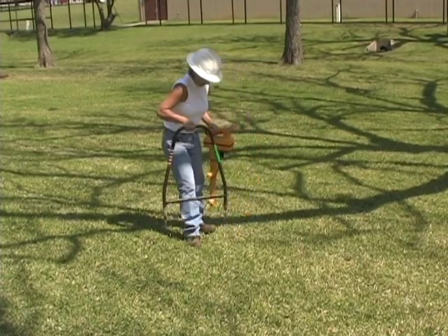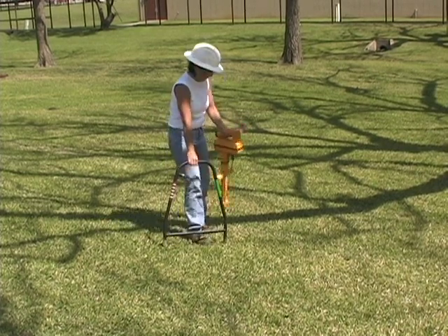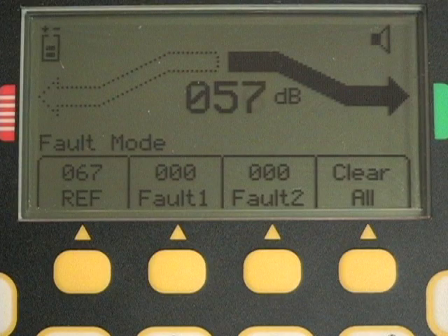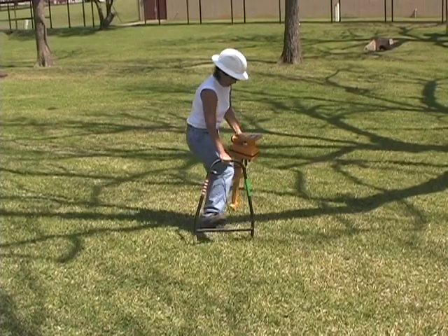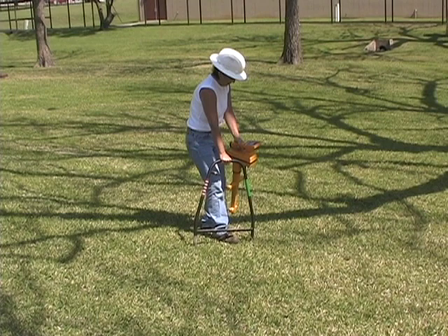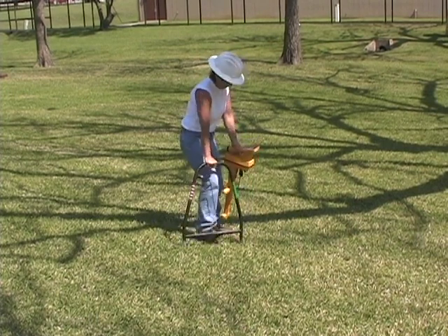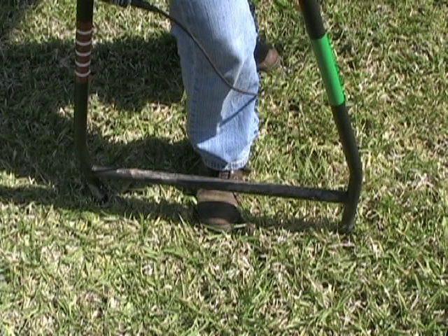Turn the A-frame 90 degrees over the center point that you have just pinpointed. Watch the receiver screen for an indication whether the red or green leg is closer to the fault. Probe the ground moving left or right toward the red or green indication on the receiver until the arrows reverse again. Center the A-frame over the fault.